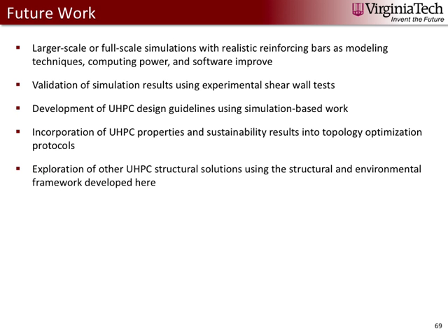So for some future work that could come from this research, larger scale or full scale simulations could be performed with realistic reinforcing bars as modeling techniques, software, and hardware improve. Validation of our simulation results here could be performed using experimental shear wall tests as they become available. Development of UHPC design guidelines could take place using simulation-based work.